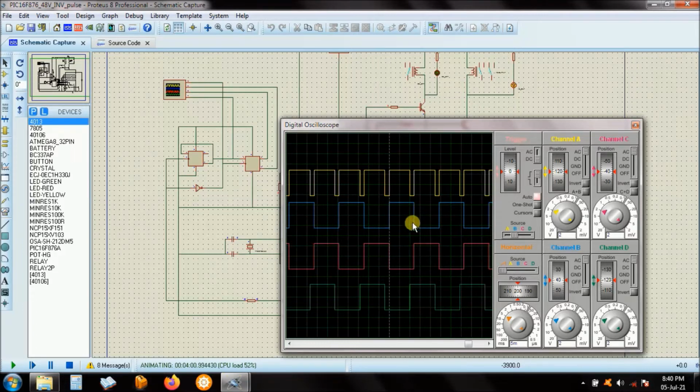One is the top, the other one is the bottom MOSFET, and these two will actually be similar. When this one is high, the other one is low, and you choose which one is top and which one is bottom. But now if I add like this, you see that the signal behaves like this. This is the output signal that we want. But basically the trick is,